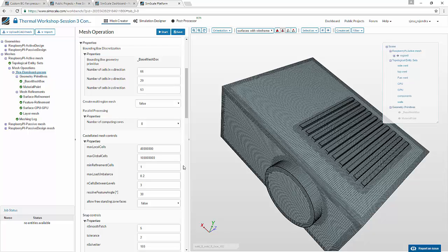So basically, this is the OpenFOAM snappyHexMesh, and you have many properties. To start with, the number of computing cores. The basic stereotypical notion would be that for any geometry, we choose the highest number of cores, and that would give us the result as soon as possible, which is not actually true. What happens is you always have an overhead.